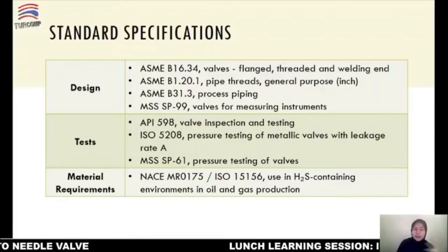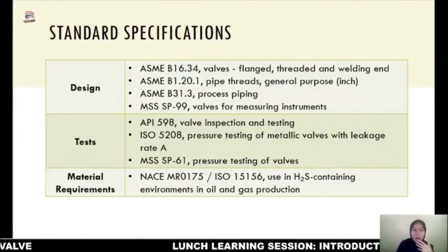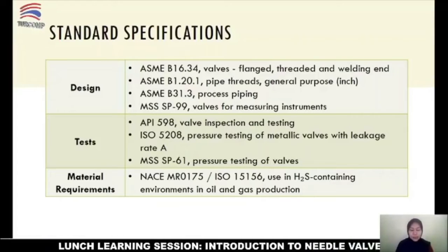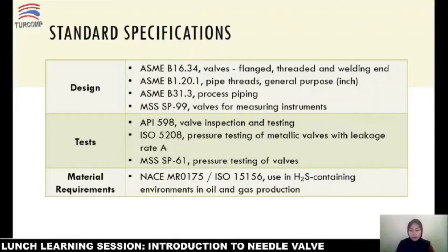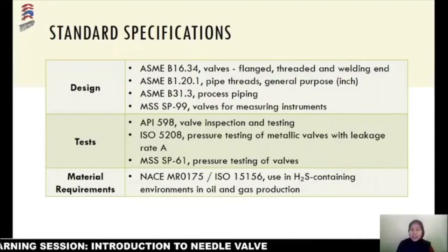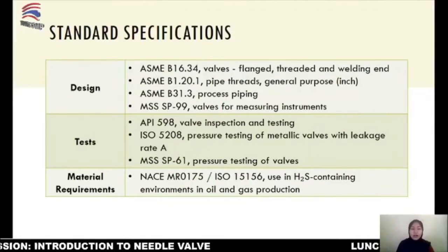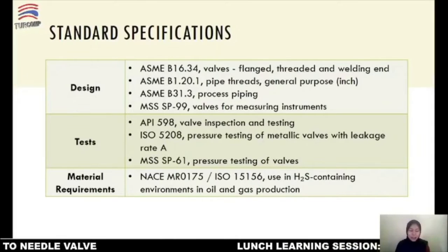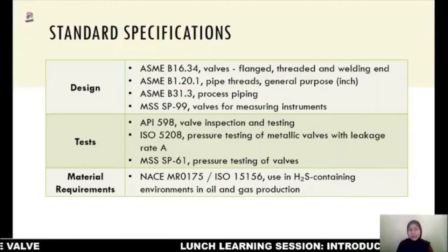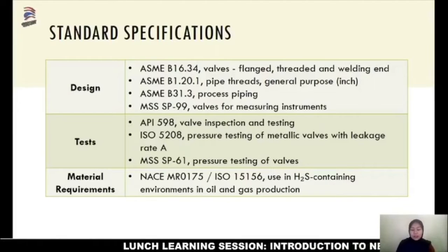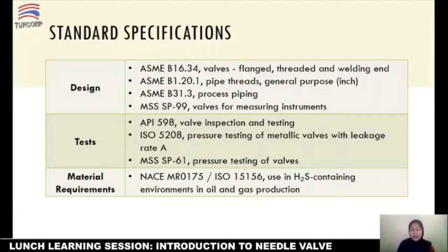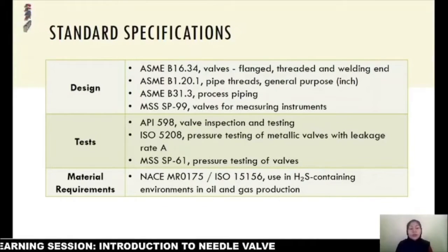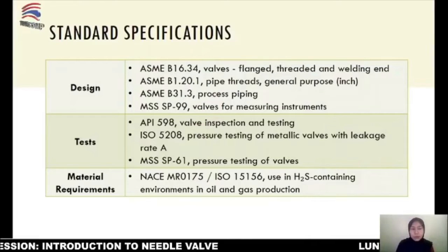where sometimes we wonder how the code is being used and why it is very important to consider the design specification whenever we choose a valve, because this ASME code or MSS code standardizes the valve specification in terms of pressure, temperature ratings, dimension, tolerance, materials, and more.